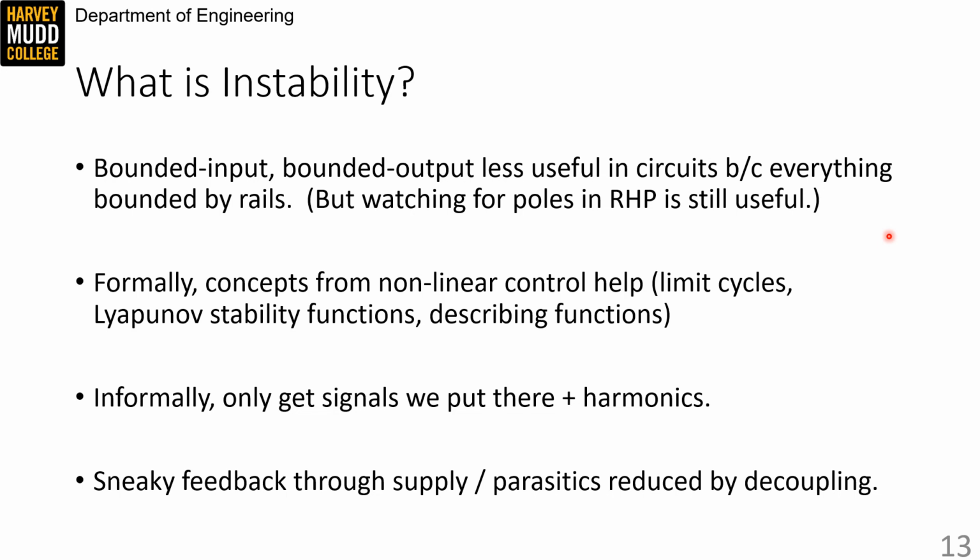So these parasitic feedback loops can cause instability even when you don't add explicit feedback around amplifiers, so always watch the behavior of your power supply and your layout when you're doing analog design, because it can cause instability. This, by the way, is why bypass caps are so important, because they make your power supply more ideal and prevent coupling paths.